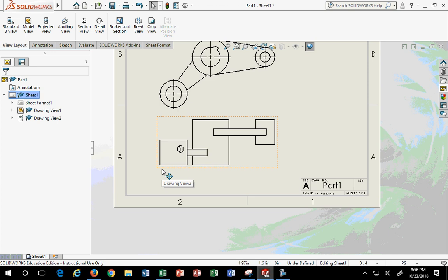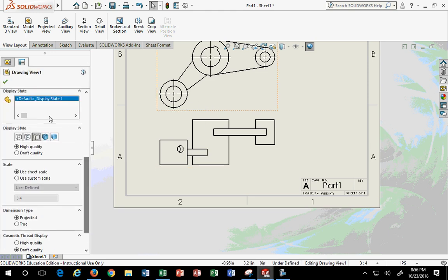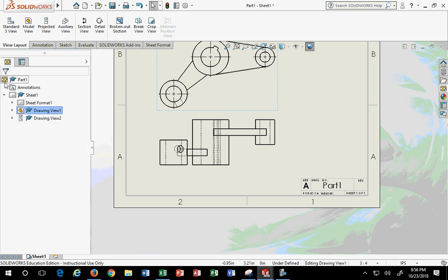Your drawing is wrong if you leave it like this and hand it to me. I guarantee you, you actually have to have hidden lines on. They're not clutter, they're necessary. So you turn them on. I did it to the primary view, so it does it to all the views. So thanks for that catch.